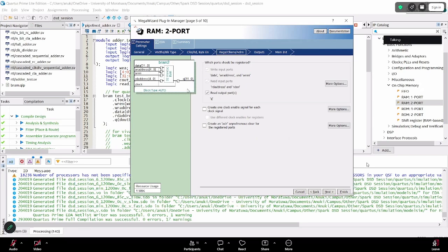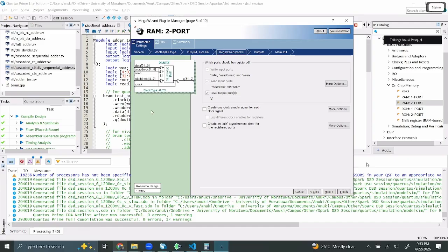You might be wondering why this is needed. This is used for the same purpose as we discussed pipelining earlier. If there are timing violations and you need to reduce the combinational path, and you find that this section has a large delay, then you can add another register to break up that path. So that's the use of this read port register. But normally you don't need that, and it's a bit annoying to deal with two cycle delay when we are using the VRAM data.